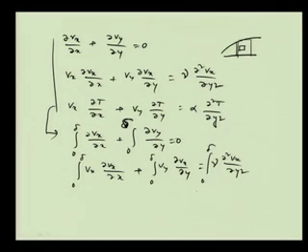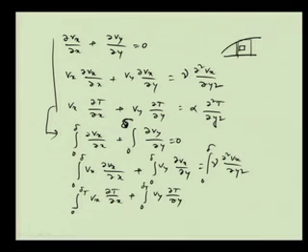Similarly, for the temperature case, we have already shown that the limit should be 0 to delta t, because our assumption again is that the thermal boundary layer is below the hydrodynamic boundary layer: integral 0 to delta t Vx del T by del x plus integral 0 to delta t Vy del T by del y is equal to 0 to delta t alpha del square T by del y square.